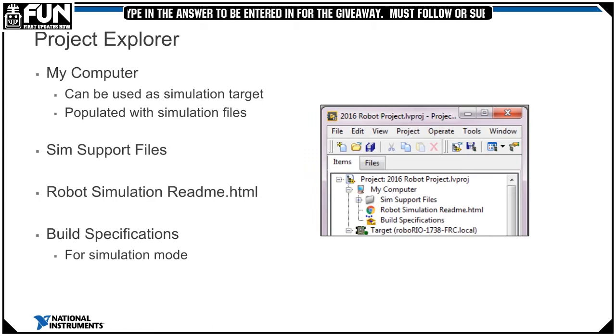So we'll just go top to bottom on the Project Explorer. My computer is up there like it always is. You can still use it as a simulation target by changing what target you're deploying to from robot main. We talk more about that in episode 2. And that's where all the simulation support files live. Again, sim support files are in there. That has the 3D CAD files and the description files for the simulated robot. You don't really need to be poking around in there. Don't put your CAD files in there. It won't do what you think it does. Just don't mess with sim support.